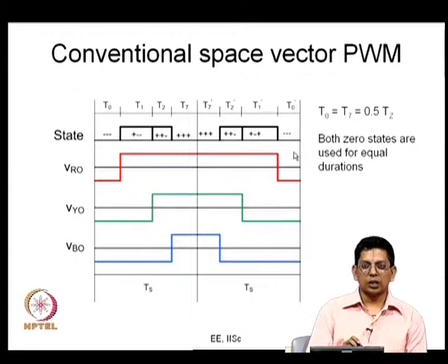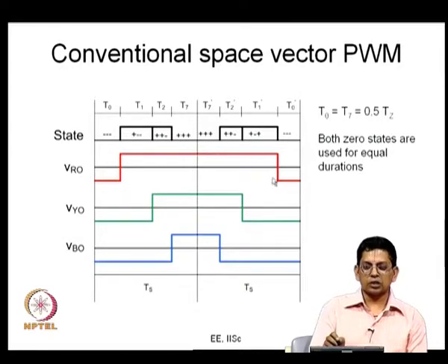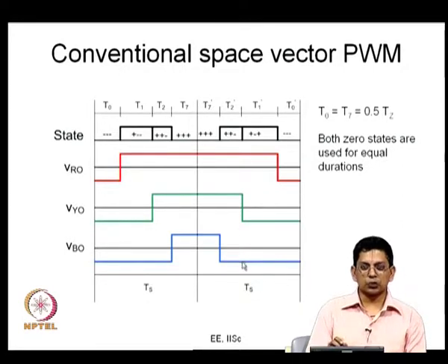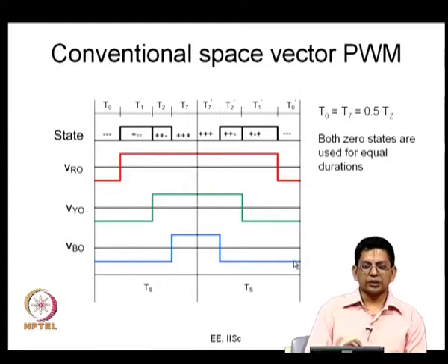That is what you do in space vector based PWM. So, the R phase voltage now varies like shown here. You see that it has the highest duty ratio of the 3 phases here, and Y phase has a duty ratio which is kind of close to 0.5, or an average voltage close to 0, and VBO has the lowest duty ratio, as you can see from here.